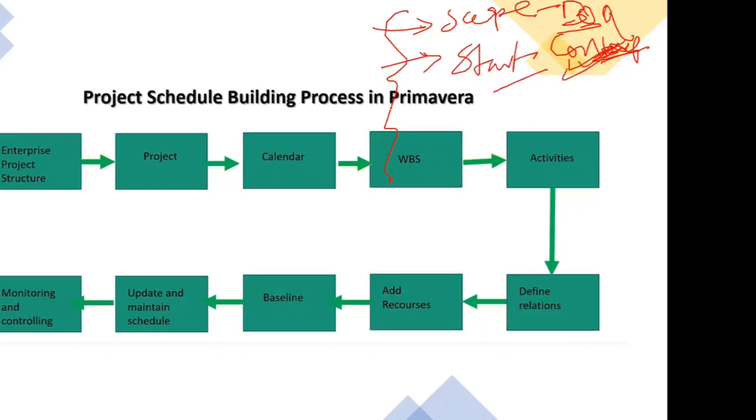Okay. Now, what again you need is start date of the project, from where you'll get this contract. Now you need to know the calendar. What is the calendar you are going to follow, right? You are going to work 10 hours in a day, or maybe 8 hours in a day, or 12 hours in a day. You are going to work on Saturdays, Sundays, 5 days, like whatever is the calendar you first of all need to decide, then you can proceed further, right?